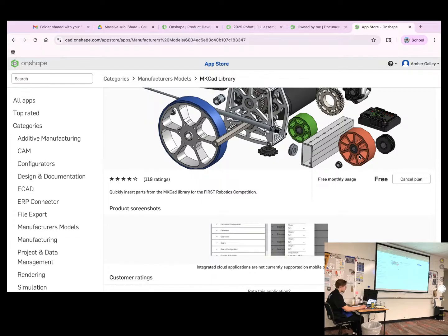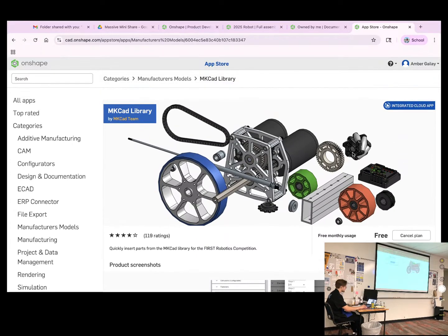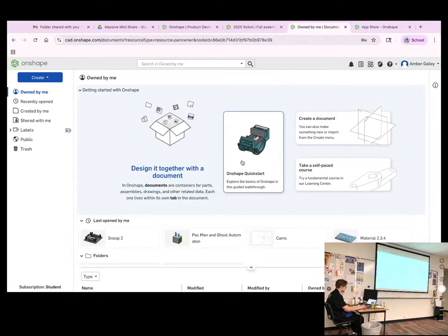Most teams don't like this, but it does make it legal. You can take the big breaker out and put in a small one. But if it's on your drive motor for your swerve drive, you're not going to like the results, because it's going to trip the breaker, and then you're going to be dead on the field until the breaker cools and resets.